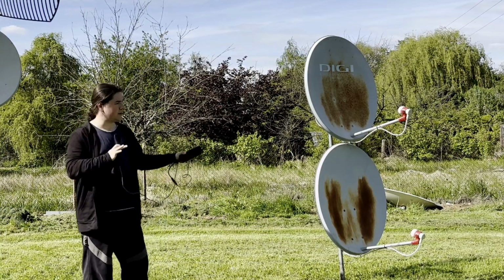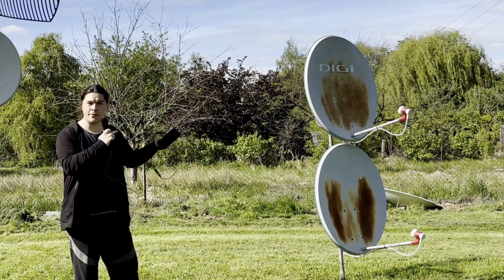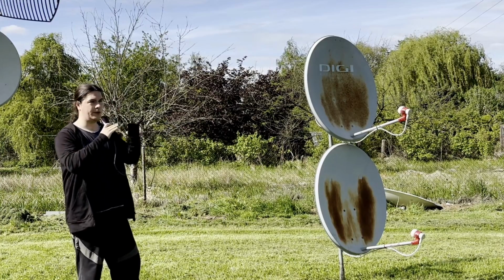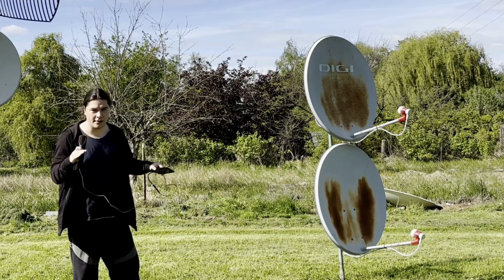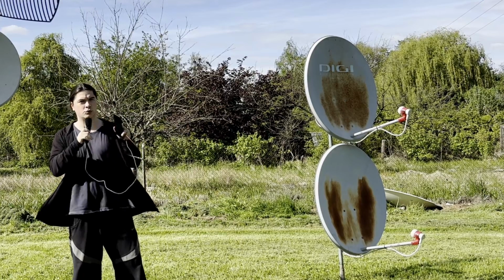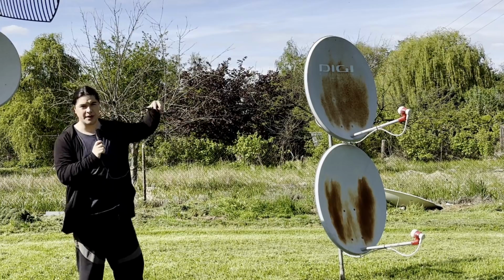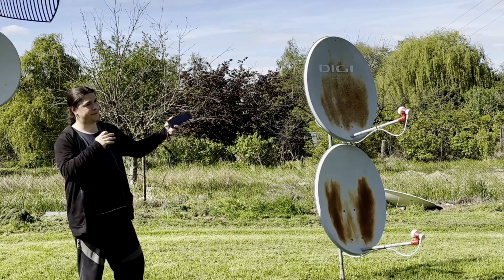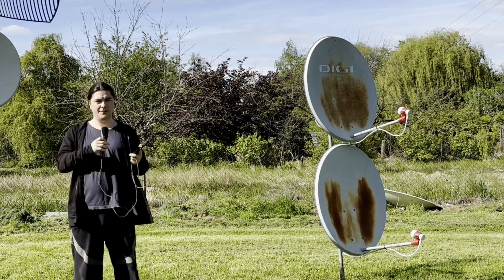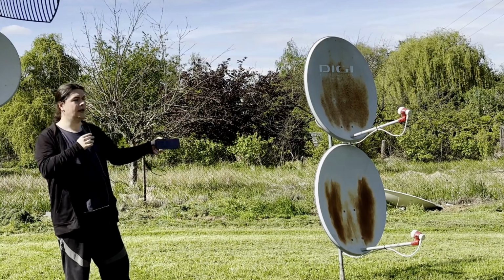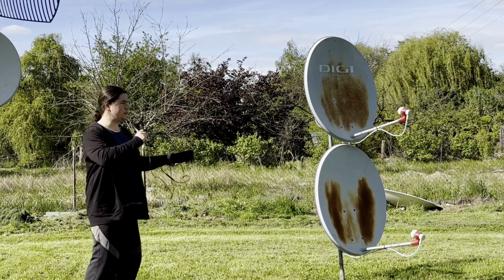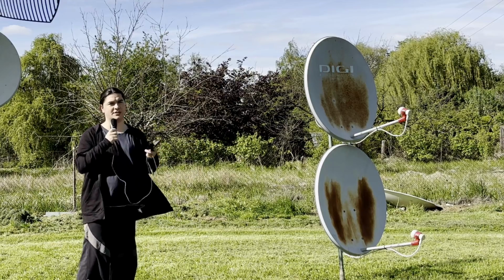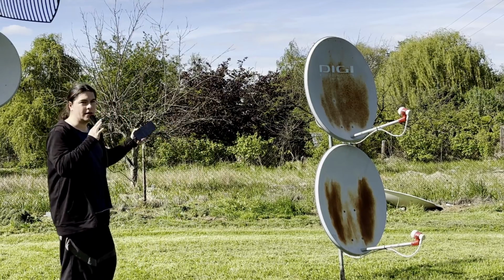So you can set up everything, connect everything except the power input of the LNB. You're going to see the noise floor of the SDR, and then you power up the LNB, and what you should see is the noise floor jumping up as the LNB starts up and starts amplifying random noise coming into the dish antenna. If you don't see that, maybe you can try raising the gain of your SDR, or maybe you have a loose connection somewhere, but that's generally the indication that the LNB is working.